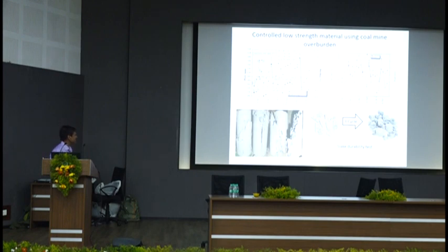After 3 cycles, see the shape of the aggregates was like this. Now it has become very smooth. Based on that, they define a factor called the slake durability index. Based on that slake durability index, a classification is there for different types of rock. Based on that, you can say how much the durability is. Because if I feel my material is strong, and I can use it like a rock material, then I can go for it.